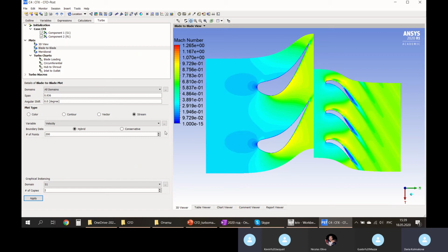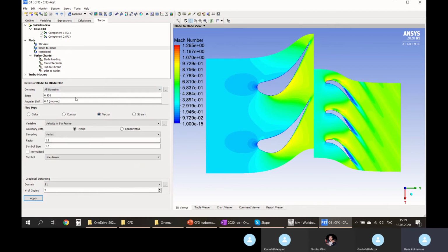I mean, maybe you've selected the wrong rotational axis, or you set up bad boundary conditions and so on. Then of course you need to follow the vectors and streamlines of your flow in your turbo machinery. If there are a lot of problems in the structure of the flow, like a lot of separations, you can see, just a second, I will show you.